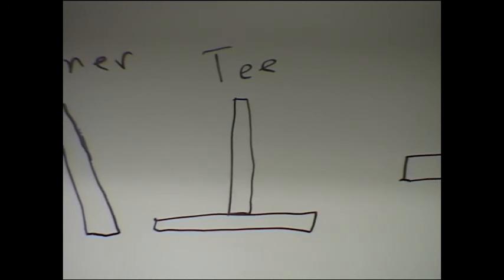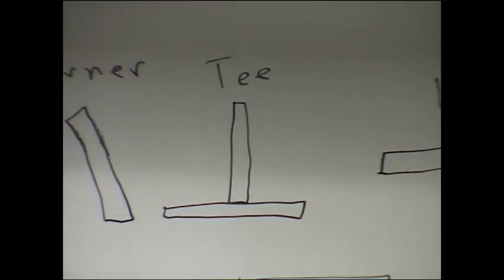Okay, now they actually do heavy plate and pipe with oxy-acetylene too. And they do it with a high test welding rod, okay? And it's kind of a different animal. You have to use big tips, big everything, higher pressures on your oxygen and stuff like that. Okay, but I mean, it's gotten quite uncommon anymore, but it's still actually done in places.